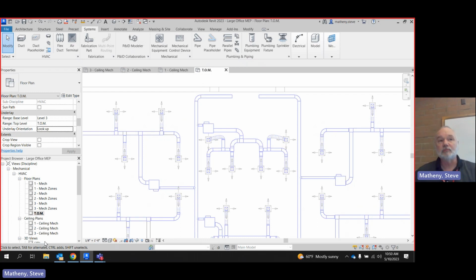If they ever have to replace that whole entire unit and it's on the roof and it's sealed, very tough to do. If you put it about a foot up off the roof and you put supports around it, it also makes it easier for them to get in there if they need to disconnect that plenum that comes down out of there for some reason. So we're going to put ours about a foot up. We're going to do about a foot offset.